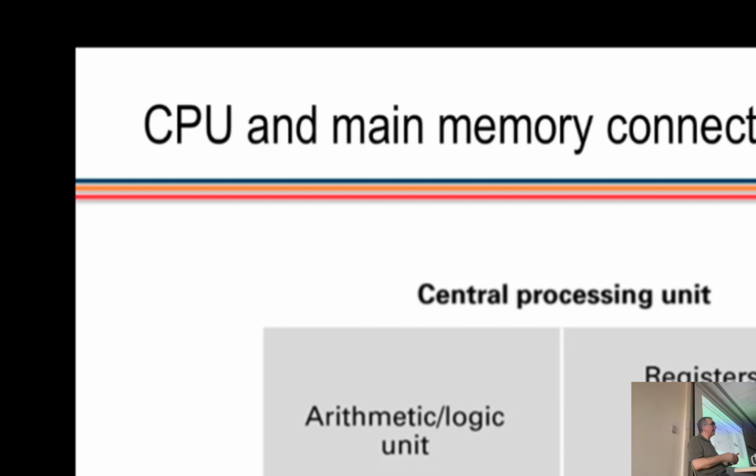So typically it can be negligible, but it is not negligible when you are designing a CPU in high speed like gigahertz range, because in gigahertz range those delays add up and could be significant and limit the CPU maximum clock cycle.